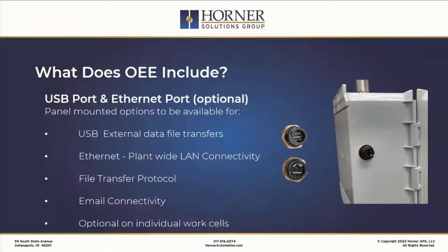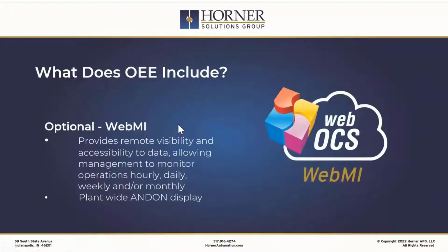We also have added 2 ports to the outside of the enclosure, one of them for the USB connector that we'll use for doing data transfer of files. And the other one is an Ethernet port that we can use to connect up and push data to the data concentrator, as well as do FTP file transfers and a few other email option type things. As I mentioned, the WebMI product is something that's available on the data concentrator, and that's what we use to push the screen information out to the clouds or to a web browser.